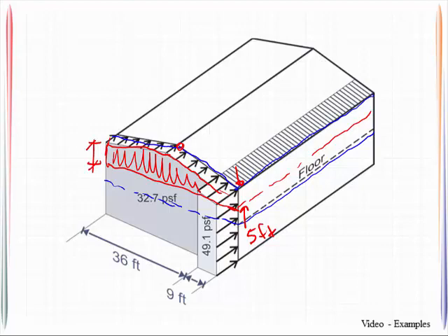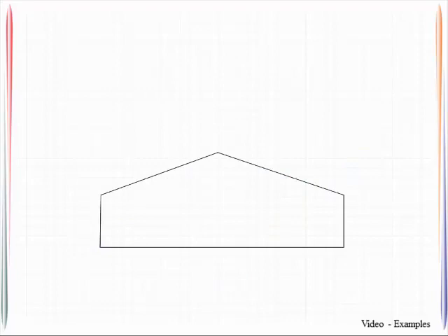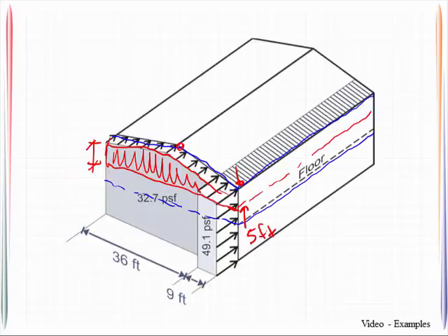In fact, let's look at that area head on. Okay, so here we are. We've got this as 5 feet, so this is just the tributary area to the roof, and it rises another 3 feet. If we look back at this sketch, we will notice we've got a lower pressure over that 36 feet and then a higher pressure over the 9 feet.